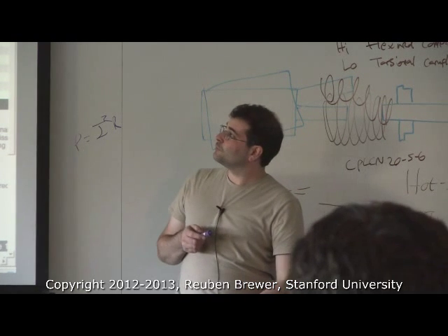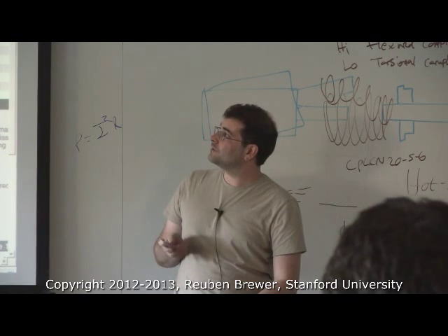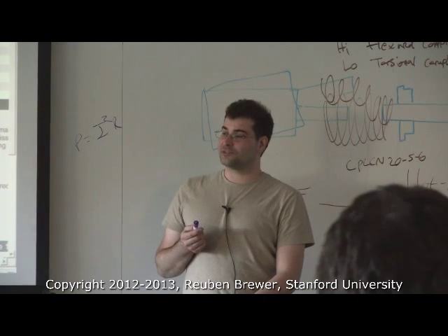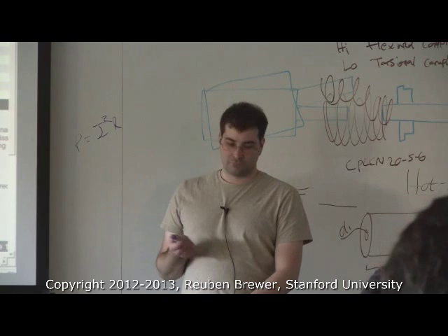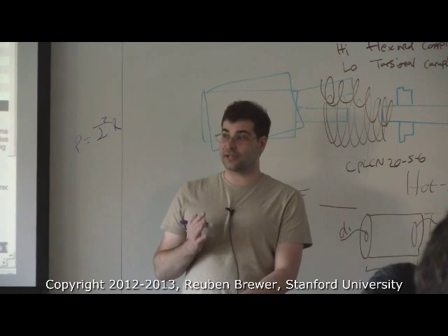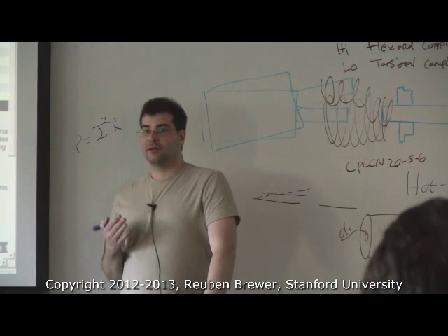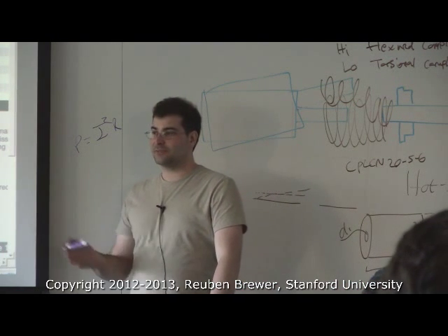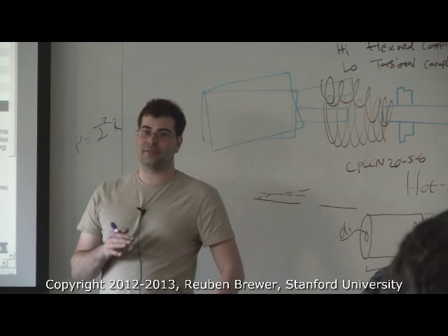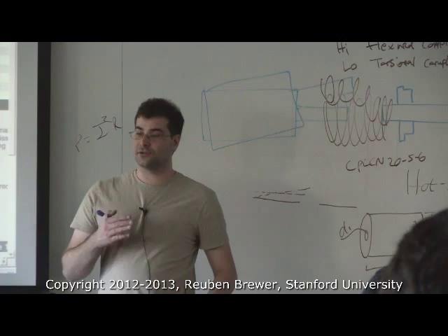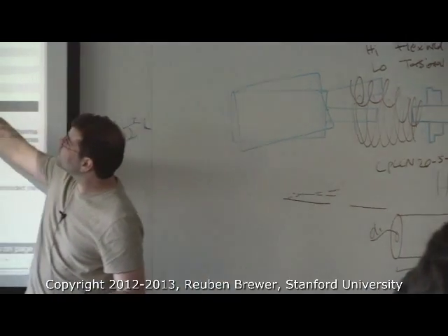So the reason I say this, we had a PhD, Kurt Salisbury, do a haptic device in our lab, and in his papers he did peak current. That's completely legit because literally everyone who does this does that to make their haptic device look better. But just keep in mind, you can't actually buy that haptic device and use it at those peak currents because it will torch.